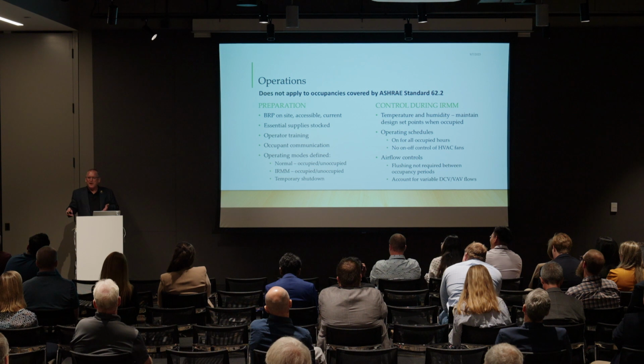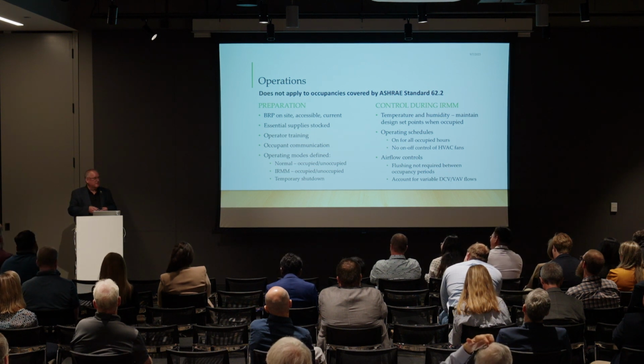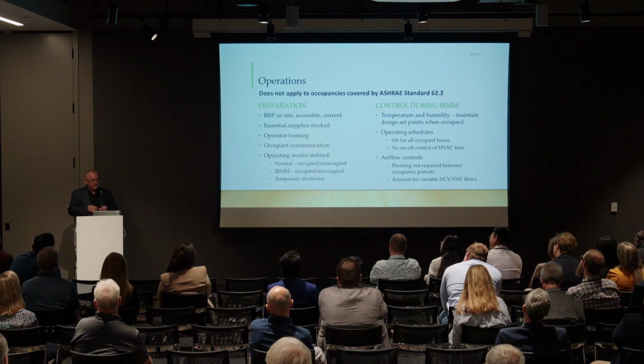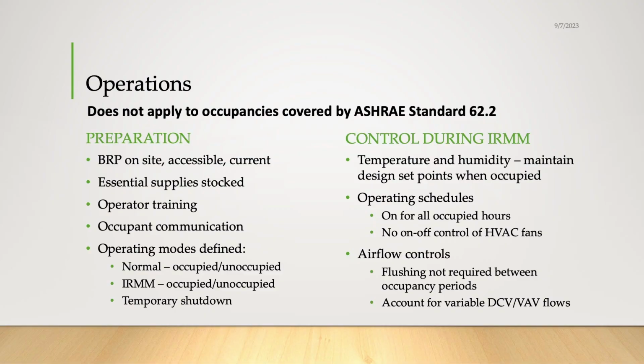And we had a problem with filters also. You know, there was a run on MERV 13 filters when ASHRAE said that would be a good idea if you upgraded to MERV 13. So that's the importance there. We also need to have operators trained on the special operating modes. We need to have communication with occupants about what we're doing. So all of that stuff has to be in place, and then these operating modes should be defined and in the control system so that we can make quick, graceful transitions.